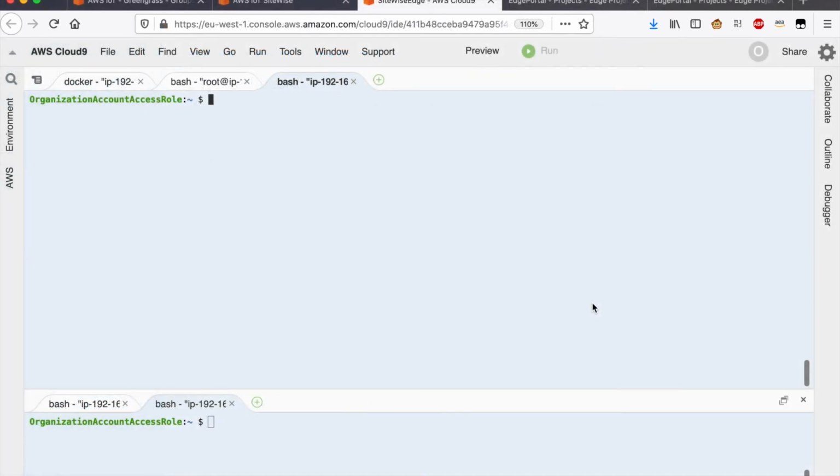In the last part of the demo, I want to show you how you can query the API at the edge. That is the same API like in the cloud, but you need to use another endpoint, your local endpoint. First of all, let's list the asset models. What you can see here is I use the normal AWS CLI. The service is called IoT SiteWise Edge.